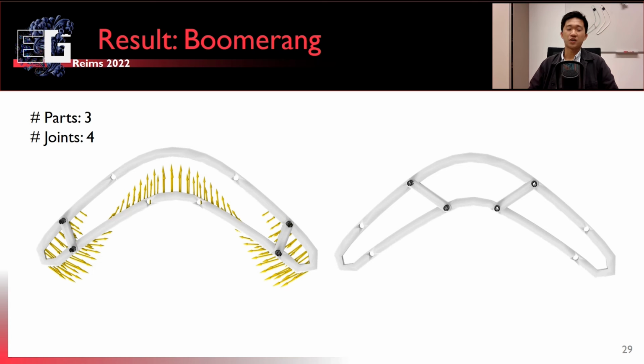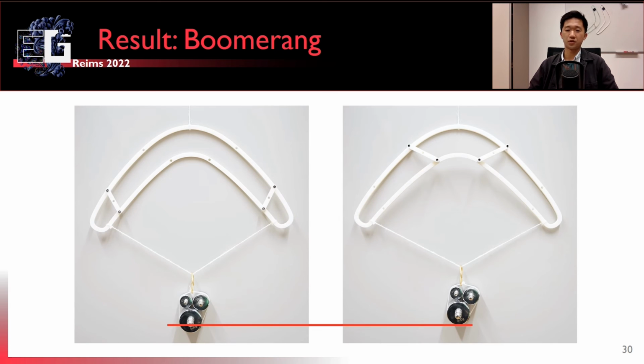And we also tried some continuous optimization. So here's the boomerang example again. We want to use the gradient-based method to change the initial supporting part. So basically, we just run the gradient descent, and the inner supporting bars converge to a better position where we have a better structural rigidity. And here are the photos for comparison, and we're still applying the same loads to both assemblies. And we can see the reinforced assembly undergoes much less deformation than the initial configuration.